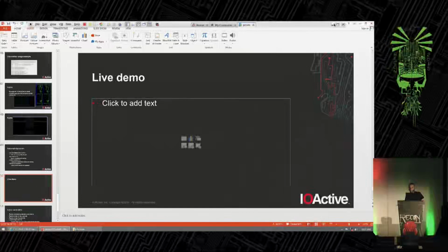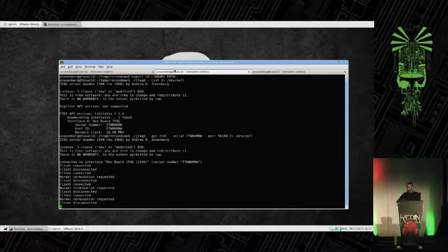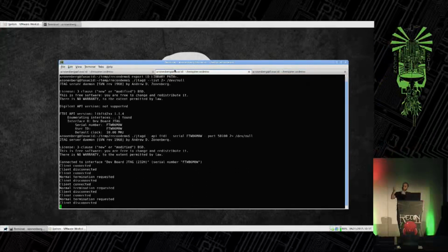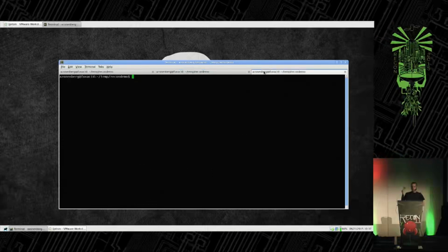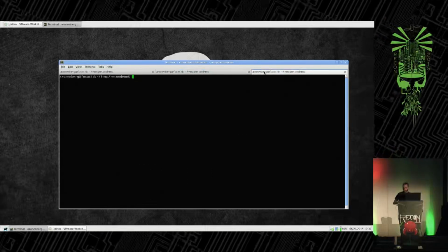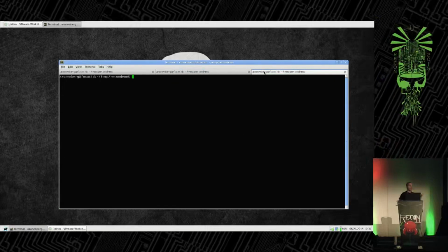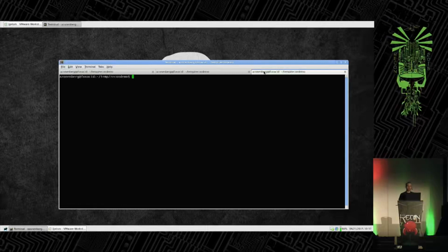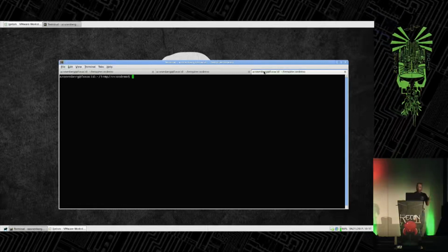I have my JTAG daemon connected already. This is my dev board. It has a small FTDI 232 on there that I'm using for JTAG. What I'm going to do is create a bitstream using libcrowbar that will act as a NOT gate and a buffer, and then bit bang inputs going into there with the FTDI chip. We should see one LED and then the other alternately lighting up.